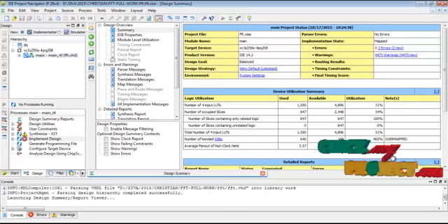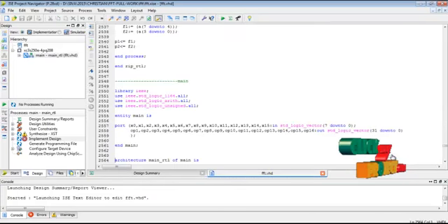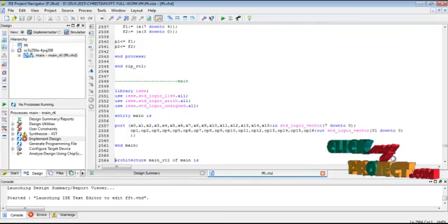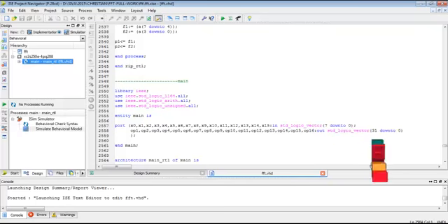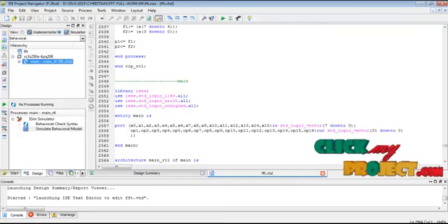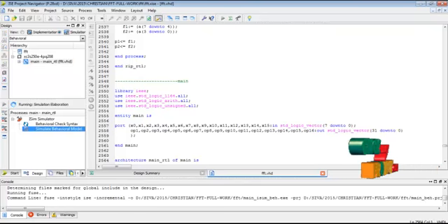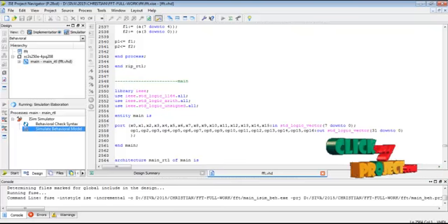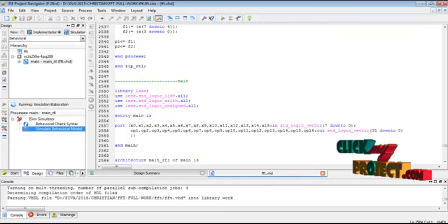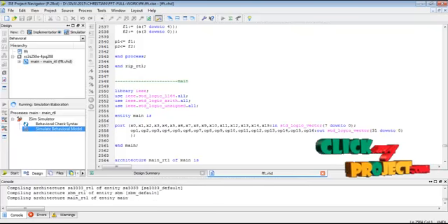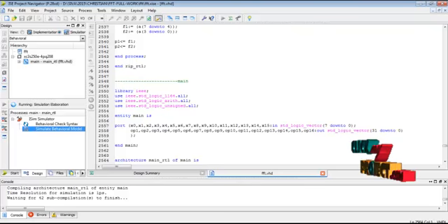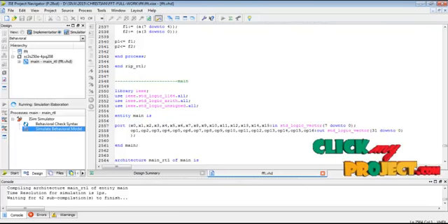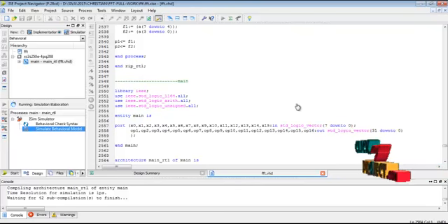Then we open the Xilinx ISE project and select the main function, which represents the inputs and outputs present in the overall FFT architecture. Then we select the simulation process for simulation performance analysis. Then we simulate the FFT architecture and run the final output process. This process was compiled successfully, and we open the Xilinx ISim simulator. This is used to simulate our overall FFT architecture. We apply the given input data bits separately and get the final data bits for the overall FFT architecture process.